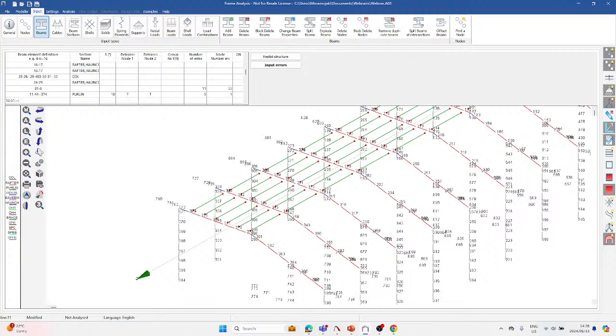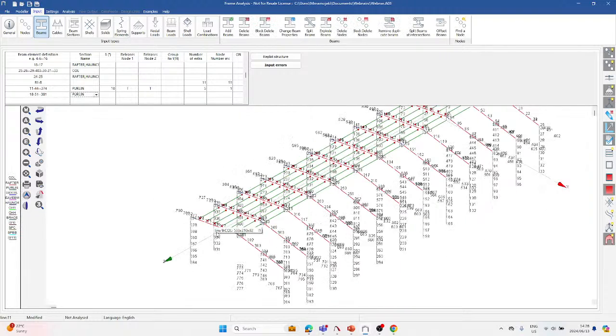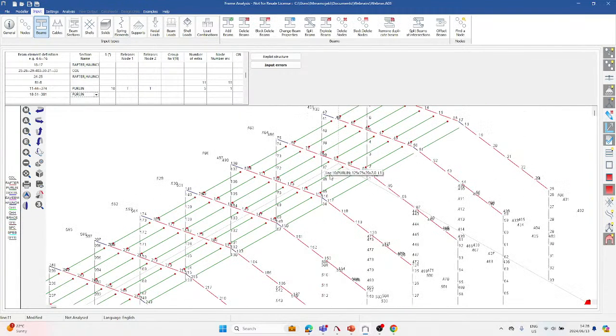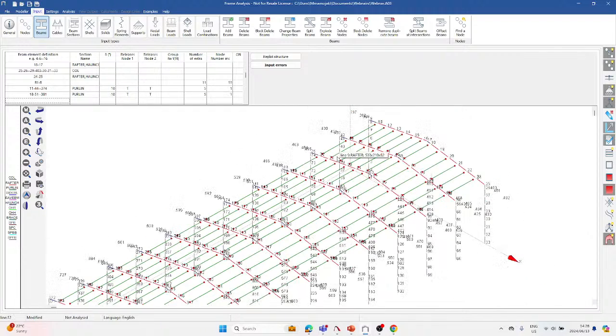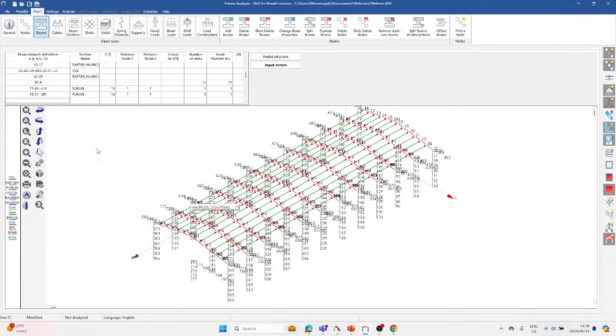and then 18 double hyphen 2 381 purlin. So that's the purlin there, over there. Also it'll be minus 10, the rotational angle, because it's on the other side. Also 5, node increment is 1. So there I have my purlins, and then I'm gonna define my side rails.